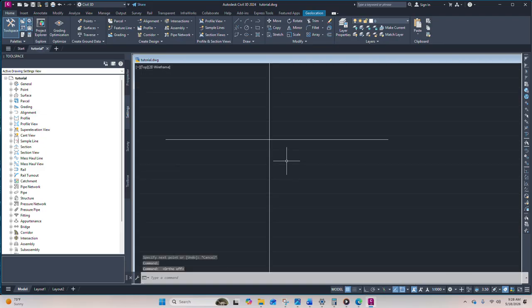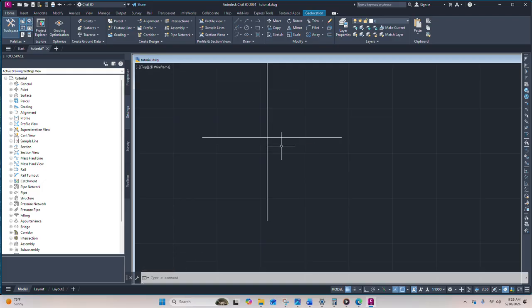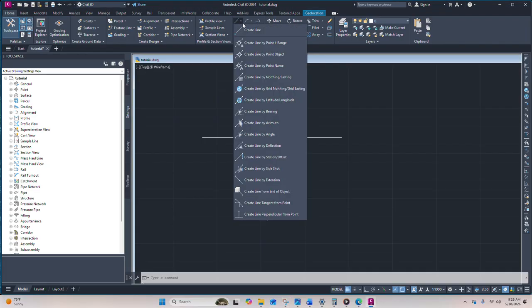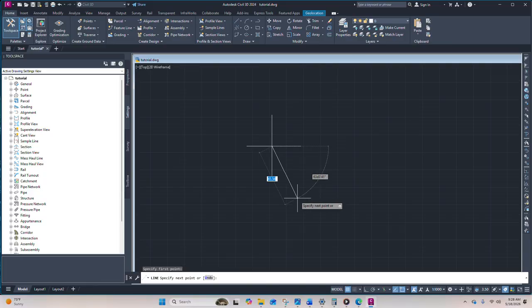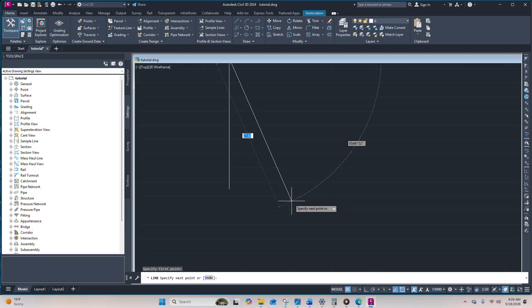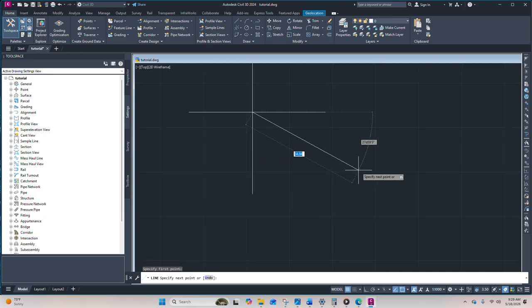So we start. This one will be V2. Let us draw 43. So we select the line tool. It tells you from the command line to select the first point. Our first line will always be at the center of our whole circle bearing. From our keyboard, let's type the distance. The distance is in blue, and the bearing will be in white. So 43.